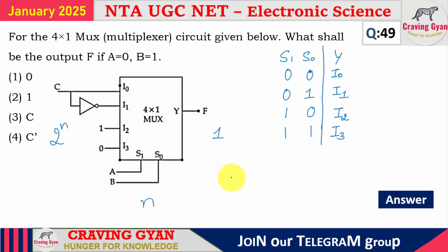Right? Able to follow? For a 4x1 multiplexer, what shall be the output if A equals 0, B equals 1? A is 0, B is 1. Nothing but which case? 0, 1. In the case of 0, 1, what will be the output? The output will be I1 data. What is I1 data? C given to a NOT gate, it is C bar. So option 4 is going to follow.